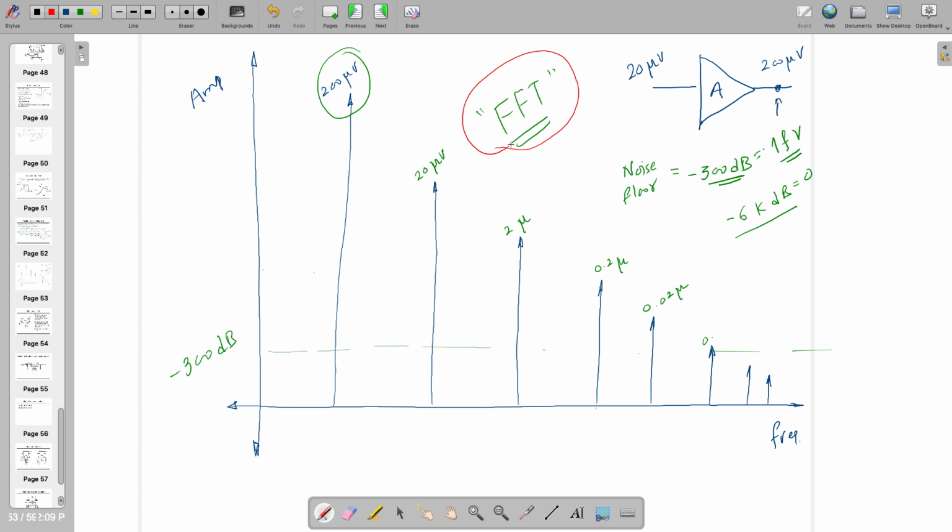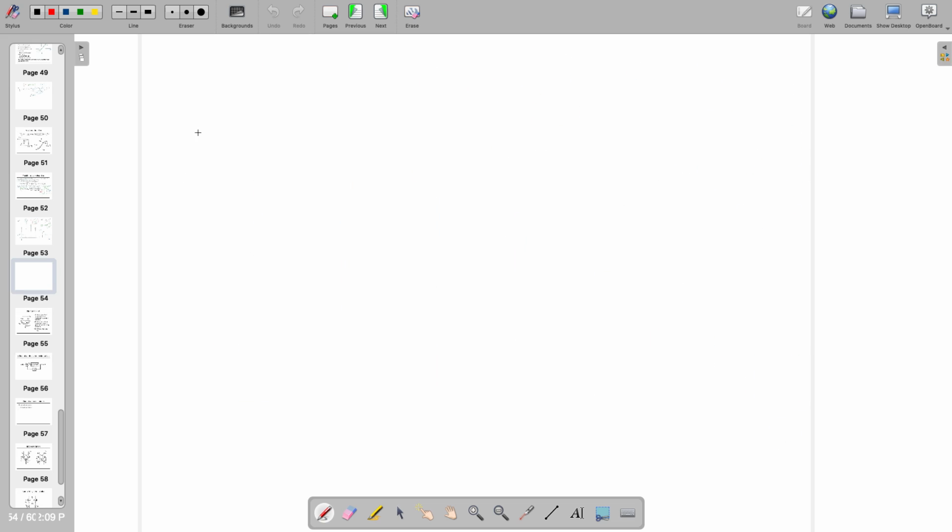So what I suggest is, take one sine wave in Cadence. Just do this exercise. Find out the FFT of a sine wave. So what are you going to expect if you have sine omega t?